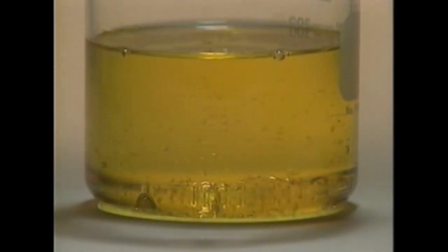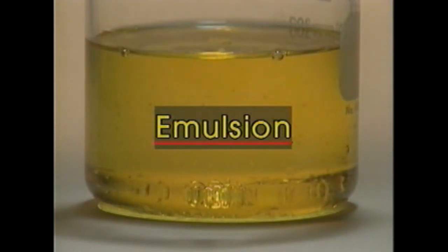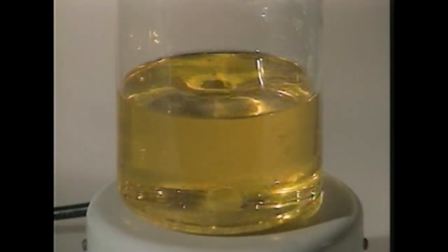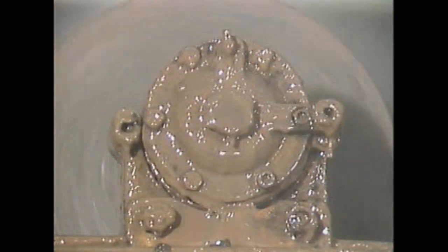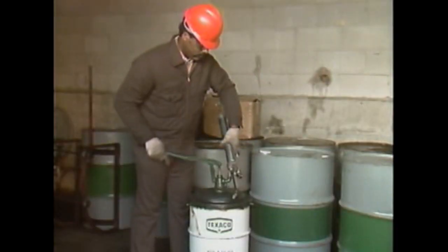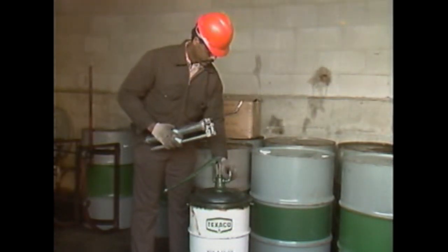A lubricant's resistance to forming an emulsion is also important. Basically, an emulsion is a mixture or suspension of components that are difficult to separate once they've been combined. The process that causes the formation of an emulsion is called emulsification. A lubricant that resists forming an emulsion is usually desirable because an emulsion of lubricant and water has poor lubricating qualities. Equipment manufacturers generally specify appropriate lubricants for their equipment, depending on how the equipment will be used. In turn, workers are responsible for making sure that they use the type of lubricant that's been specified.